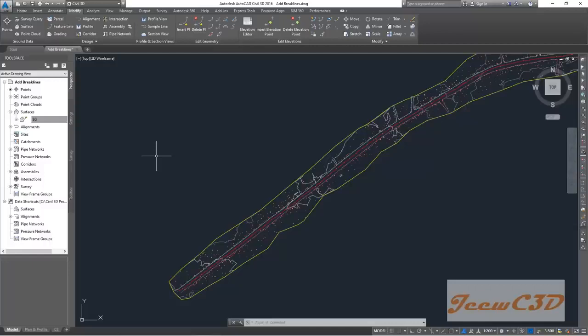So now we are going to close everything, and from the next point onwards we are importing the exported Land XML surface. That means we took the surface out of the drawing. Then in the next video we will take it into the drawing. Actually it will be into a new drawing, not this current drawing. So after exporting this, I want you all to close this drawing by saving it.